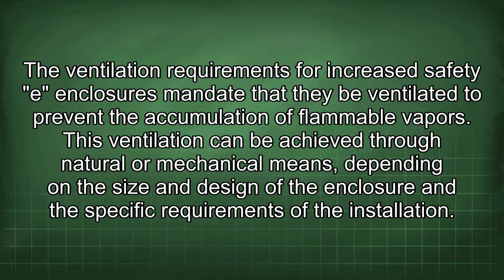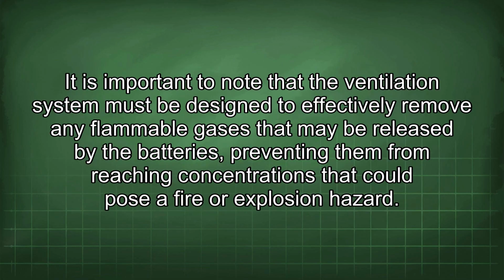This ventilation can be achieved through natural or mechanical means, depending on the size and design of the enclosure and the specific requirements of the installation. It is important to note that the ventilation system must be designed to effectively remove any flammable gases that may be released by the batteries, preventing them from reaching concentrations that could pose a fire or explosion hazard.